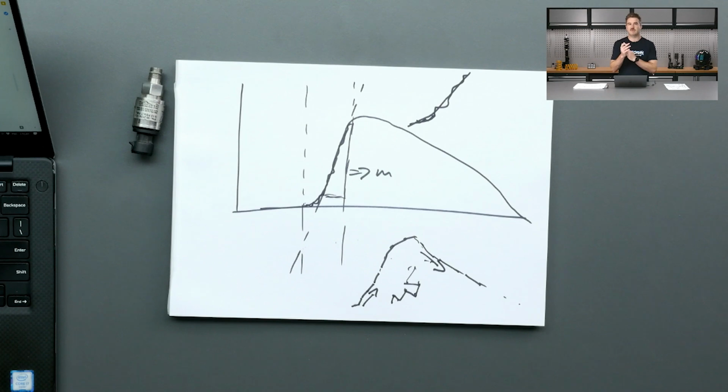So first we're taking the derivative to say only calculate the aggression when we're increasing the brake. Then we do smoothing the channel, and then we're taking the derivative of that channel. After that, you can do things like looking at either the maximum or the average of that channel across a lap. Then you can plot that across a whole lot of different laps and look for a trend in the aggression, whether it's a difference in the trend between one driver and another, or a difference as the run changes. There's all sorts of different ways you can check that.